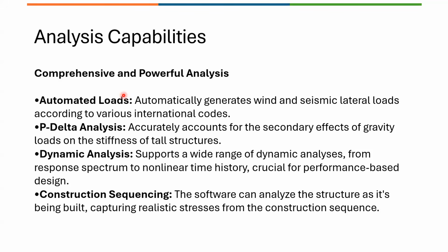We will see that in an example shortly. Then we can perform dynamic analysis. Real-time earthquake data can be an input, and you can perform the analysis to get the responses for various time history inputs. So dynamic analysis is possible, and construction sequence, if needed, can also be performed. So it covers all the required analysis tools.